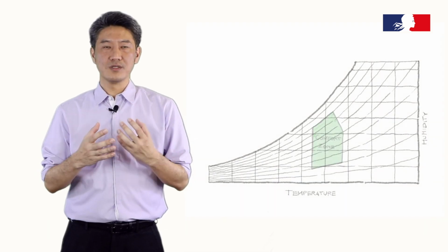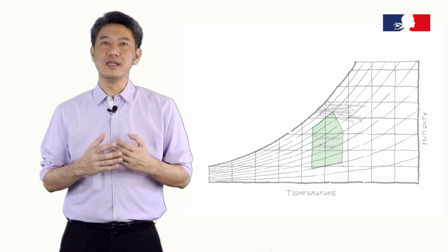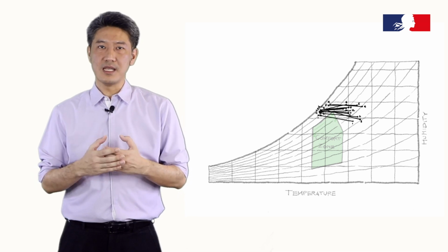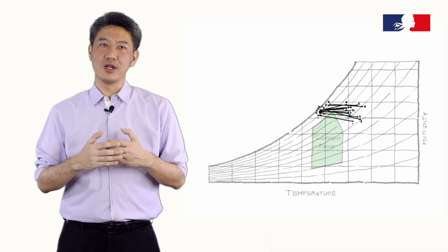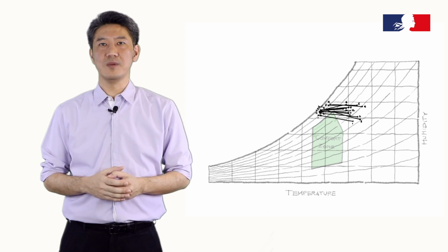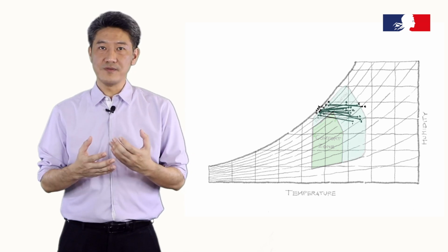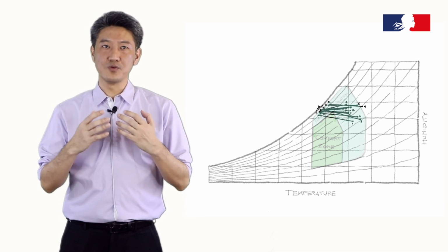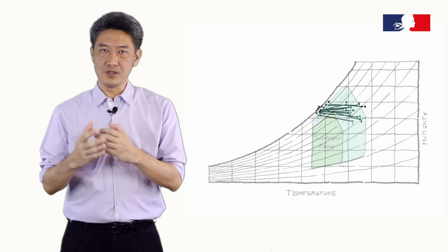Secondly, in warm and humid climates, I chose the city of Trivandrum, India. You can see that the temperatures do not exceed the comfort zone very much. Natural ventilation alone should be able to bring the conditions into the comfort zone.